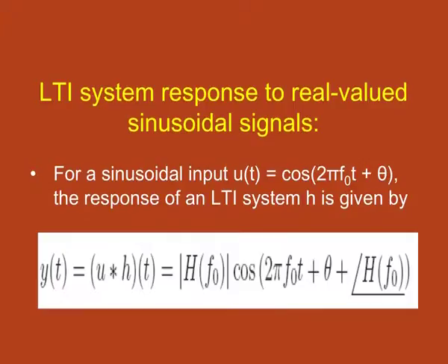Now, let us try to understand when a signal is called distorted and when it is useful, which we call distortionless. If a signal passing through a system only undergoes a constant amplitude scaling and a time shift, then we can perfectly recover the signal at the receiver side. So if a signal only goes through a constant amplitude scaling and a time shift, we call this signal distortionless.